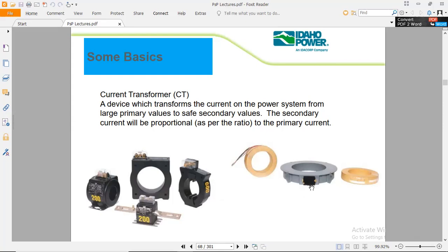And at the same instant, if overcurrent and leakage happens from a bus bar, that would be sensed by the CT in the form of overcurrent, and then it provides it to its particular relay which trips the circuit breaker directly.